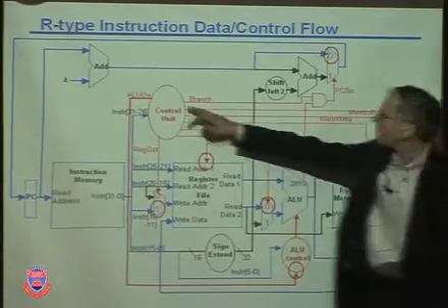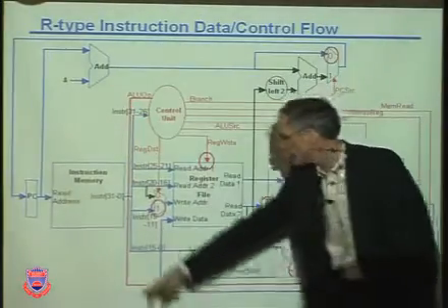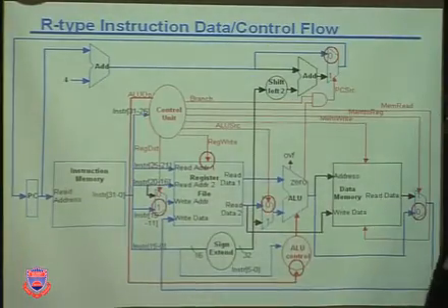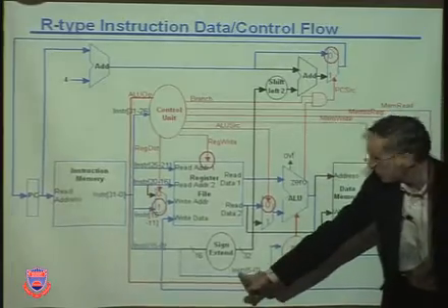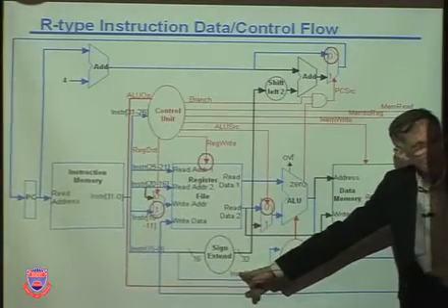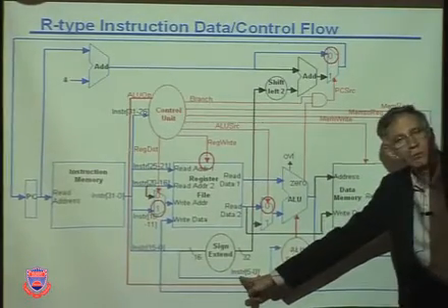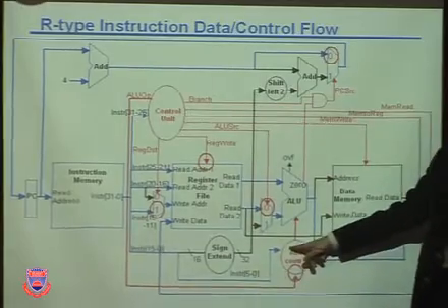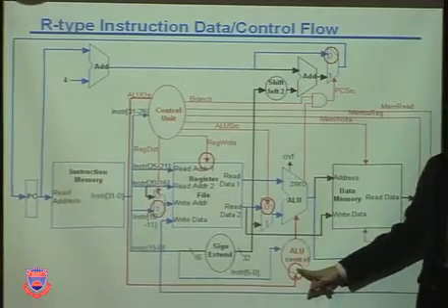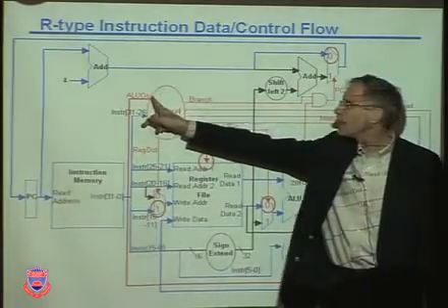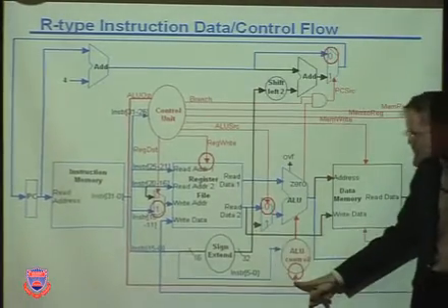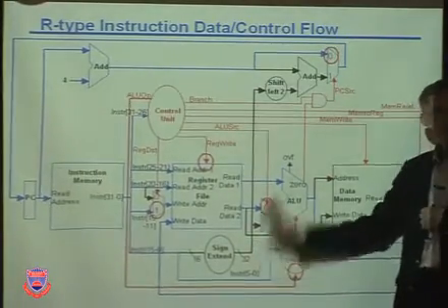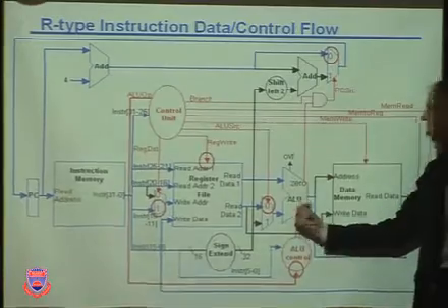The ALU op, as you see, is coming out of the control unit, coming around down here. In addition to ALU op, we need to know if it's an R-type, so we need the function field. Notice that the last 6 bits, which are 5, 4, 3, 2, 1, and 0, the function field, is going here, as well as the ALU op coming out of here. If it says it's R-type, look in your function field. If it's not R-type, this says I know what it is, listen to me, don't pay attention to him. Anyway, we know what the ALU will do.